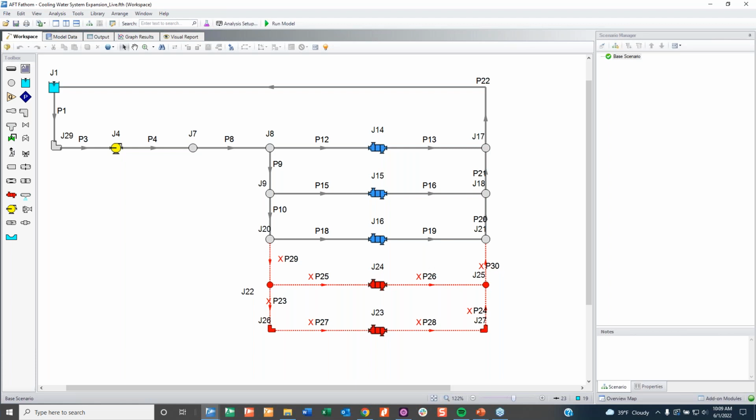You just have a pump pumping water through a system to heat exchangers, and the hydraulics are purely determined without a lot of intervention. It's just the single pump, right? So flow distribution depends pretty much purely on pipe resistance and then the heat exchanger resistance.